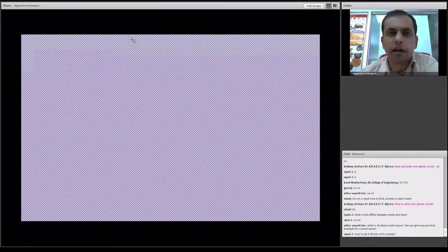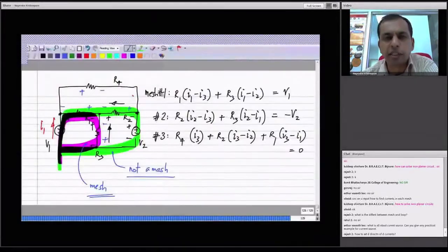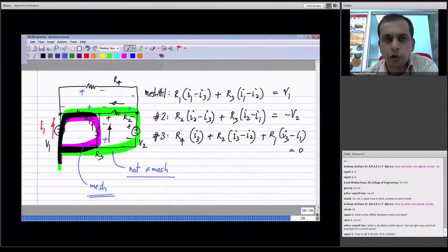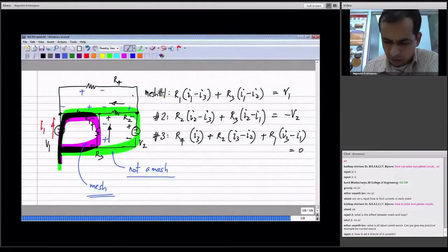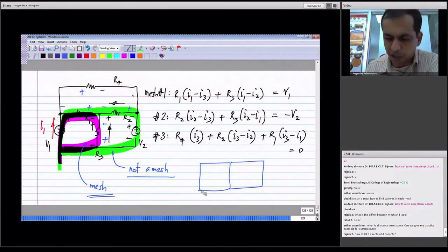And regarding the direction of mesh currents, like I said, by convention, you always take each mesh current to be in the clockwise direction. Okay. Now that gives you a nice structure because, let's say you have two meshes. I'm not showing the elements, I'm just showing the branches in an abstract way.